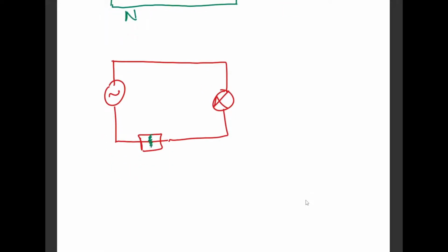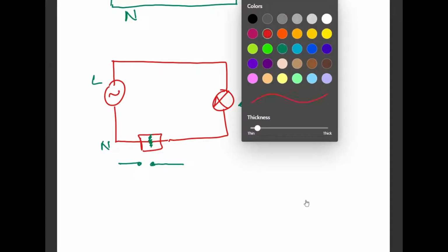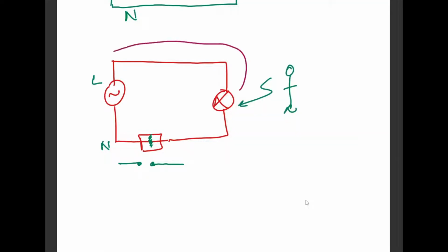But after the fuse breaks down, we see that the connection is broken, right? So this is my neutral wire, this is my live wire. If a person comes in contact with this appliance, I can see that my connection is effectively with the live wire. I'm still connected to the live wire, right? And I'm not connected to the neutral wire, which is the cold wire, which has no electricity. So this is a hazardous condition: even after installing the fuse, I have saved my appliance, but I still have not included safety for the operator.